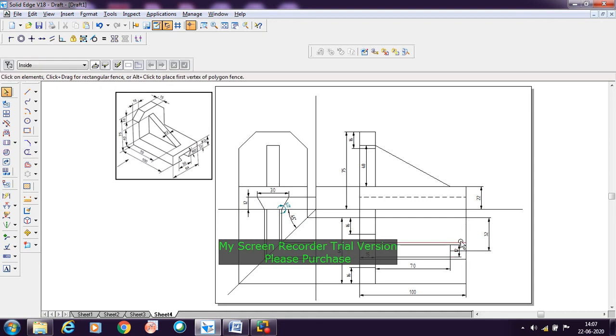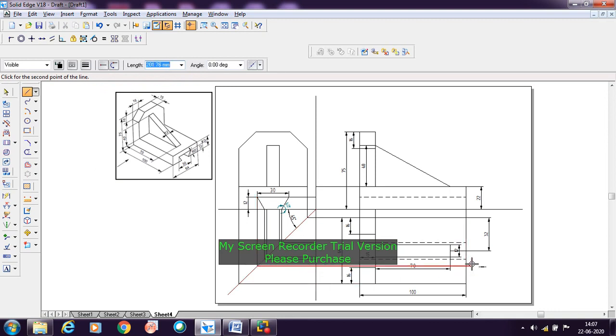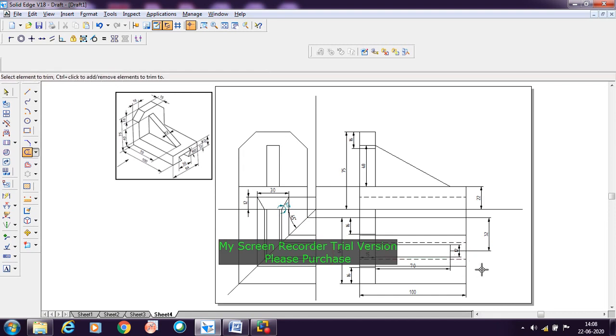These two are invisible lines. This is invisible, and this is invisible. And here, these two edges are invisible. You need to project them. So you need to extend it here until the end. Similarly from here you need to extend it until this, and then project it here. So trim the extended line here. This is not required, and here it is not required.